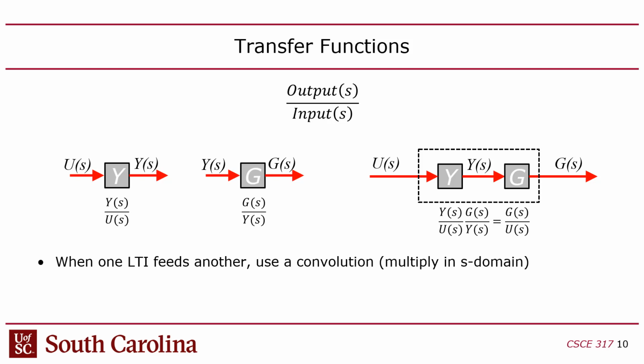Now the reason why people like transfer functions is that they're composable, meaning you can take a transfer function and feed the output of one transfer function into the input of another by simply multiplying them together. The notation is a little weird here. Notice this is starting to look like a block diagram, because that's generally how these are designed. If you go into Simulink and MATLAB, which is the most common tool for designing these LTIs, it's literally a block diagram. It starts to look like a circuit design thing at this point.